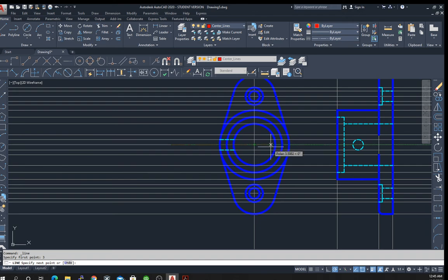And actually, we shouldn't start out by 3 inches because the diameter is 2.5. So the width is only 1.25. So we could do maybe 1.75. We start here, 1.75, hit enter, so that'll be our start point, and then we can move over by twice that, or 3.5, and that gives us that line.